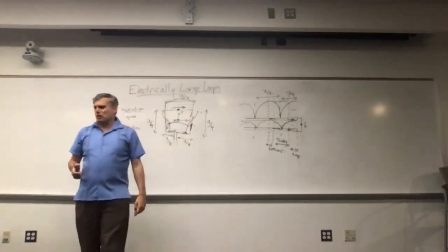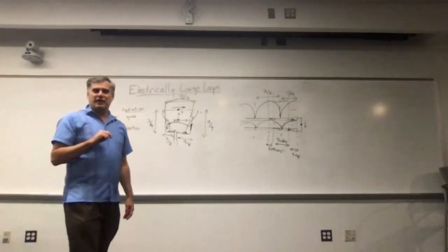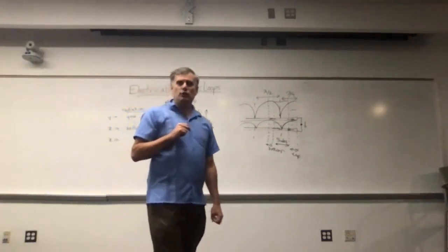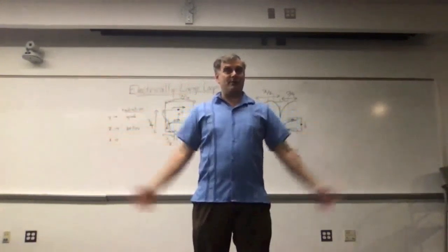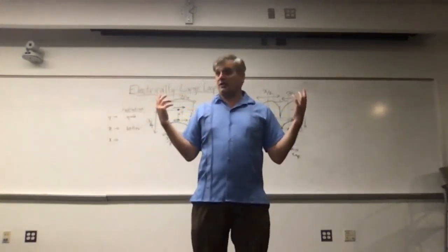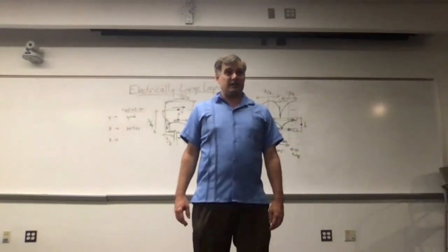This is one of the marvelous things about loop antennas. People use them often in direction finding. You say, how can you use a loop antenna to find direction? It has the world's crummiest half-power beamwidth. We're not talking about a very large antenna. You're probably lucky to get 90 degrees of half-power beamwidth out of this antenna.